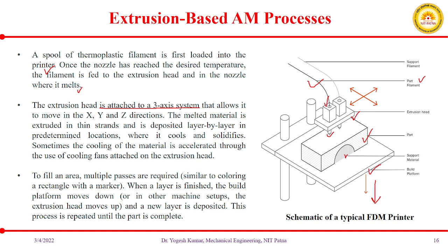it cools and solidifies. Sometimes the cooling of the material is accelerated through the use of cooling fans attached to the extrusion head. So, if you want to accelerate the cooling locally of your printed material, some cooling fans may be attached to your extrusion head. To fill an area, multiple passes are required, similar to coloring a rectangle with a marker.